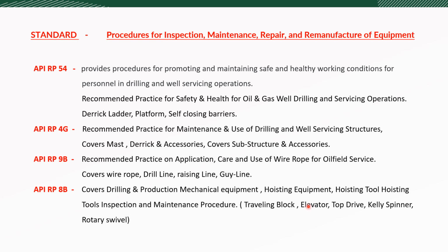No, he will have to follow the API RP 8B standard to do the maintenance and inspection of the elevator. This standard says that for all the hoisting tools used in the oil industry, the concerned engineer or technician will have to follow the instructions and advice mentioned in that particular standard.